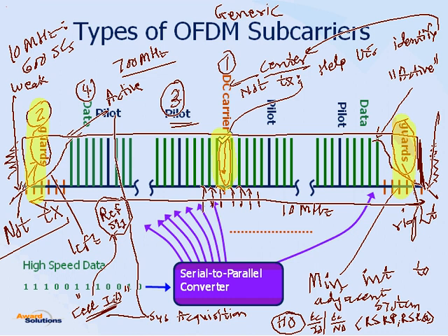Okay. And it also gives us a good idea about the channel conditions, channel estimation, and we use that to perform coherent demodulation. Meaning we will look at the pilot signal along with some data to figure out what is on the data channel.